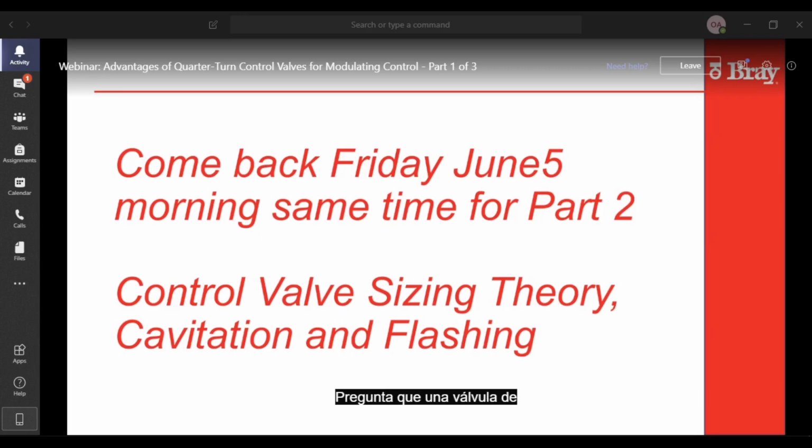That's a very good question. An unbalanced globe valve takes all of the pressure on the globe itself, and it has to be completely absorbed by the actuator. So if you change the pressure on a globe valve that's not balanced, it will react to the change in pressure. On a butterfly valve, a concentric butterfly valve has a disc that is balanced basically because it's got the shaft right in the center. So there's a little bit of induced torque. Well, at different velocities, if you're going to higher velocities, then you'll have induced torque on the shaft.